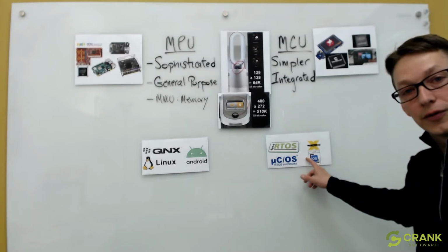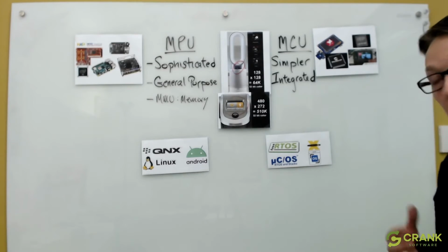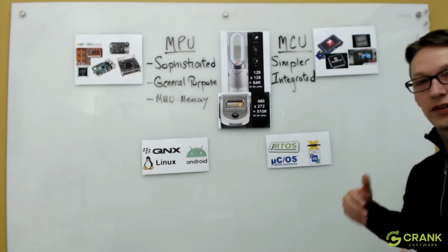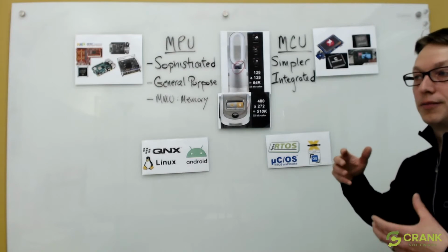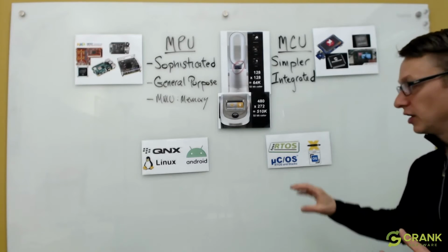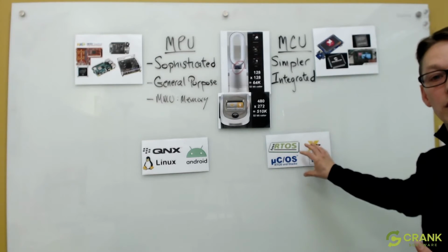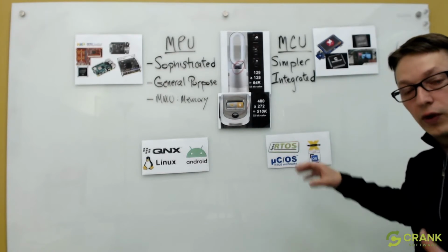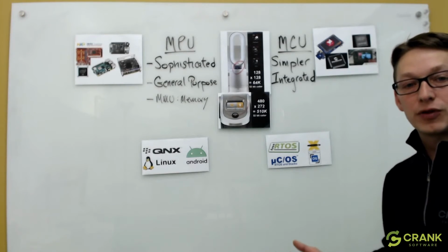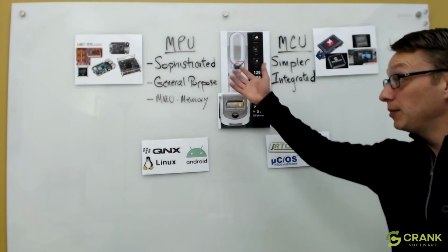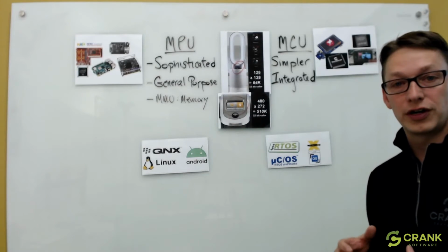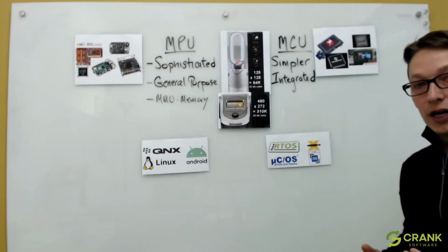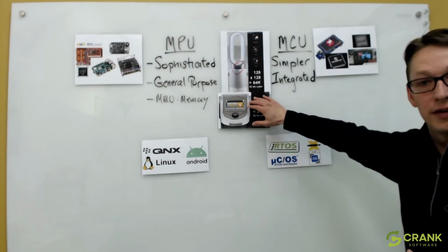So this is a slower development model, right? Now, in the context of embedded UI development, where a lot of change is happening, having to rebuild the system, flash it down, see it, find it's not quite right, and have to go make changes tends to be a slower model, so you end up using a lot more simulation techniques and a lot more scaffolding, where I'm building an application in a framework that I can execute in my desktop environment, or maybe even in an MPU environment, as a simulation for the product without always having to deal with the hardware. This can speed up development time.